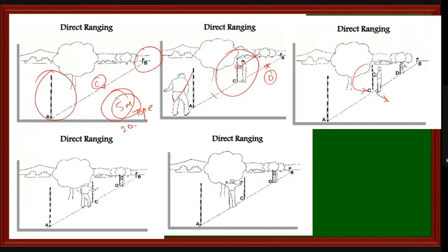Better keep your mobile in landscape mode, so you can see the figure very carefully and clearly. You can see the surveyor standing at station C with reference to station B. He guides his assistant to establish station D. When the assistant comes on the line between A, C, and B, the surveyor waves his hands up and down, which indicates to the assistant to fix station D.